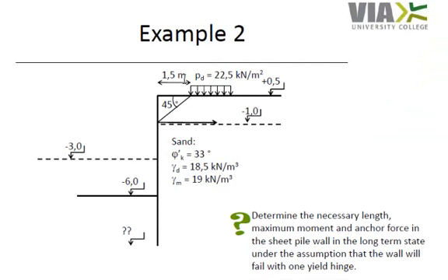and further the variable load on the ground surface is moved to act on the ground 1.5 meters away from the retaining structure, which means that it will affect the retaining structure in level -1.0. All other parameters are the same.